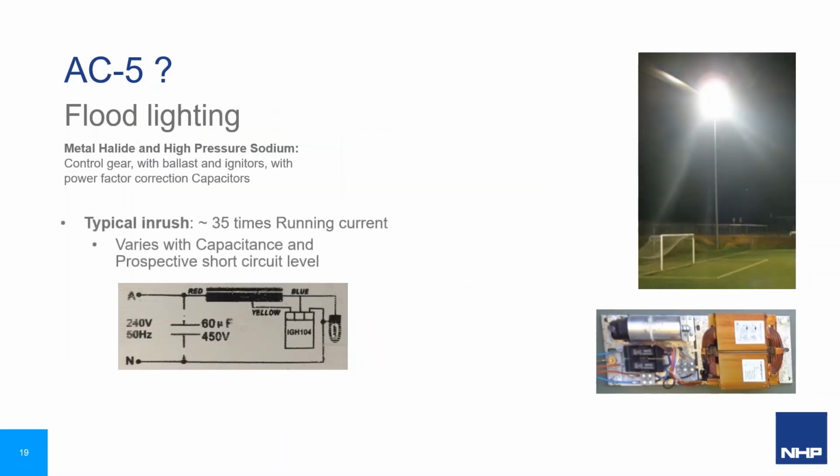Discharge lamps with inductive ballasts have a low power factor, so correction capacitors are connected in parallel with the line voltage. So upon closing the contactor, it sees the inrush current of the capacitor. Whilst it has been generally accepted that the inrush was 20 times rated current, as correction capacitor sizing has increased to provide power factor greater than 0.9, inrush levels are now much higher. The worst case scenario occurs if power application corresponds with the peak of the AC supply waveform and can be dependent on the prospective fault level at the installation.